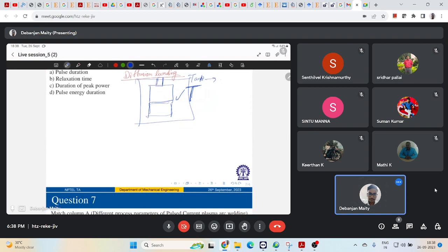So mostly depending on the material combination, the heat you provide is between 0.5 to 0.7 of the melting temperature, some kind of recrystallization temperature, along with high pressure over time.